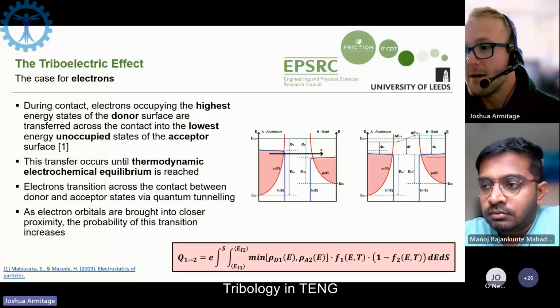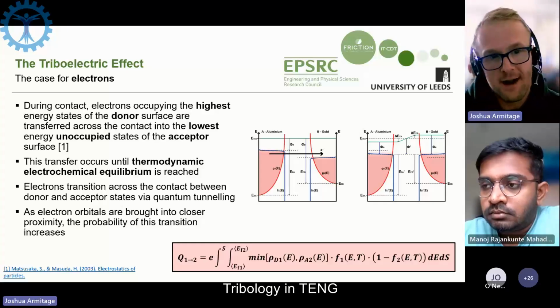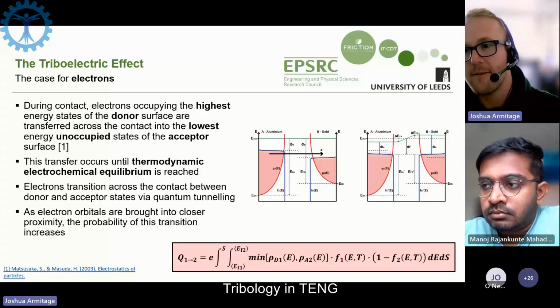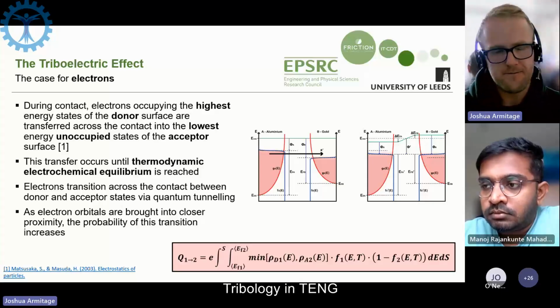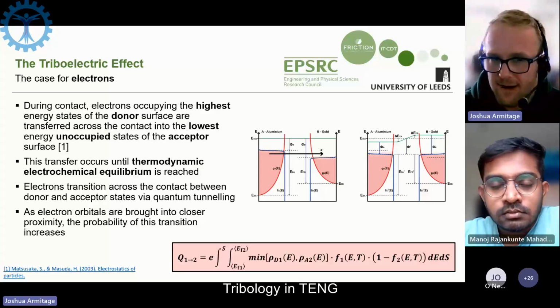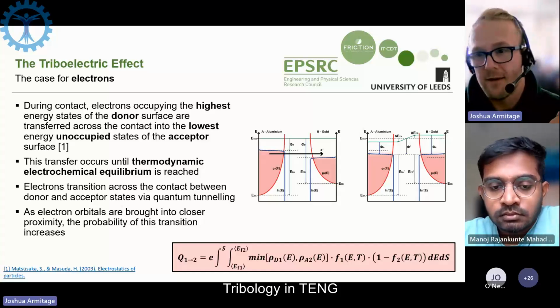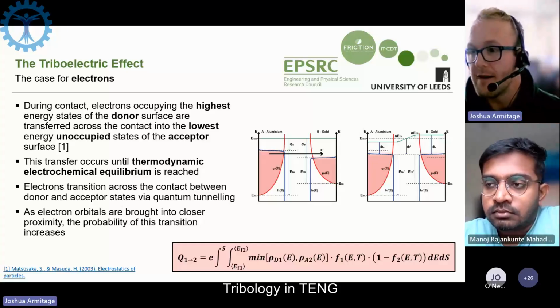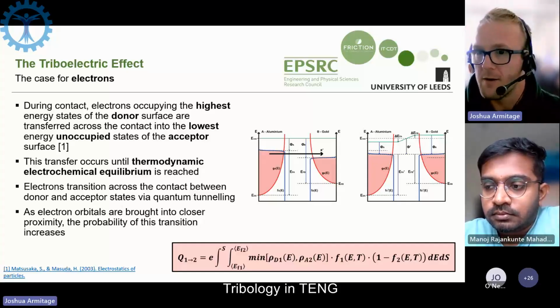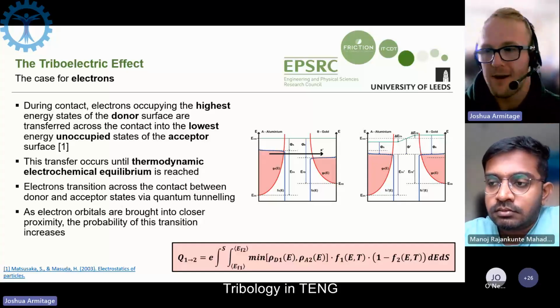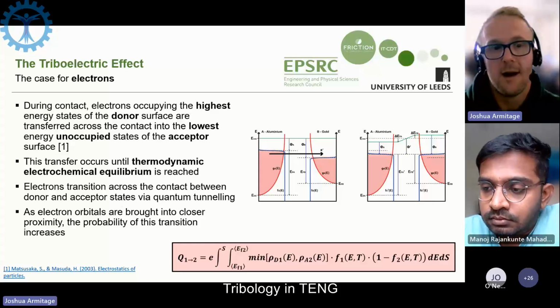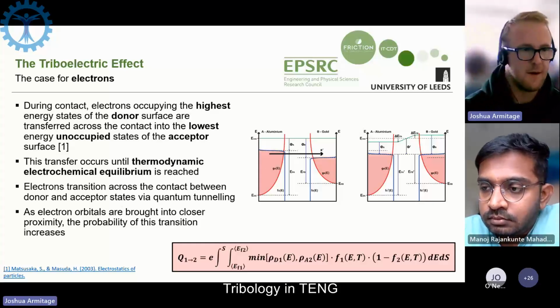So when we put the two in contact, we have electrons being transferred across from the aluminium to the gold surface. And that is an example of galvanic corrosion. When you have the two metals in contact with each other, you normally see the aluminium corrode over time. So even though it readily creates a passive oxide layer, it still corrodes in situations where you have this transference of electrons away from the aluminium surface.